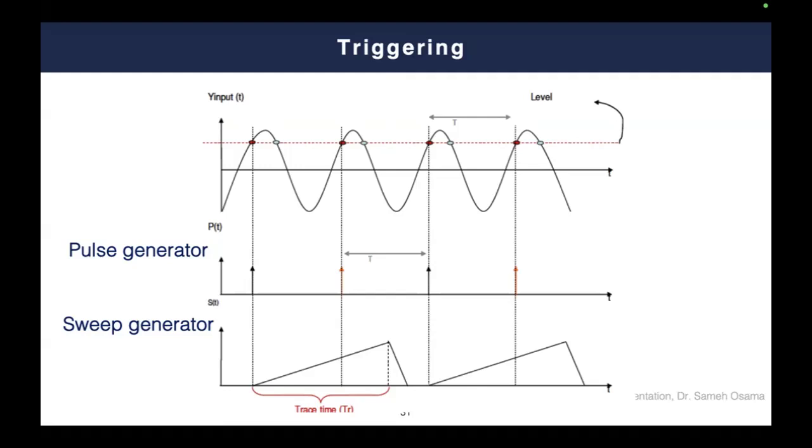You will not be able to adjust the internal trigger because simply this is a built-in feature in your oscilloscope. However, you have the capability to insert your external trigger where, in this case, you, as a user, are responsible to guarantee or ensure the synchronization in terms of frequency, of course, as well as in terms of phase.